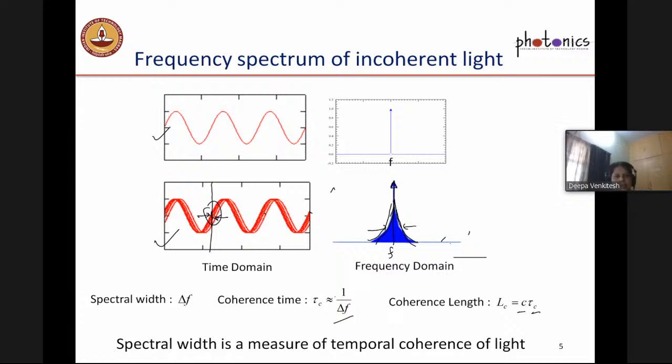So it's actually intuitive to understand the time-frequency domain pictures so that you can correlate what is happening. So suppose I have a single frequency. Let me call this sine omega naught t, or sine 2 pi times 1 hertz times t. So this is an example of a sine wave where I know the frequency is 1 hertz, which means that to complete one cycle, the time taken along the x-axis is 1 second.